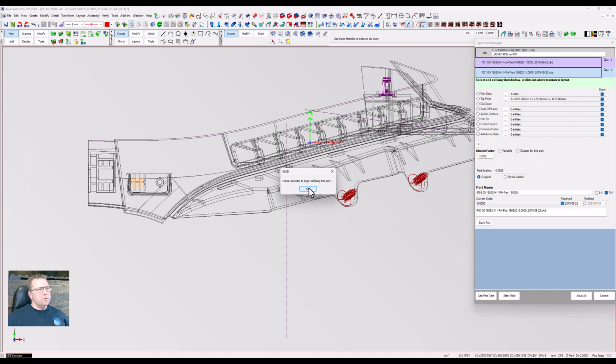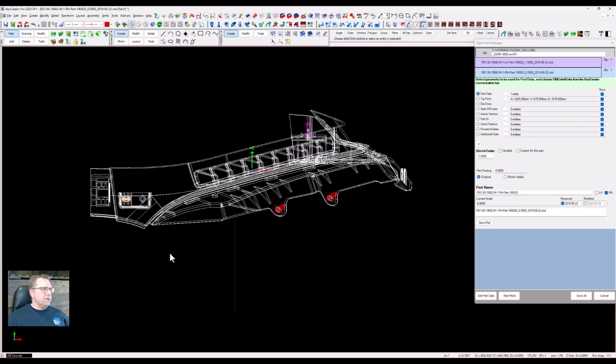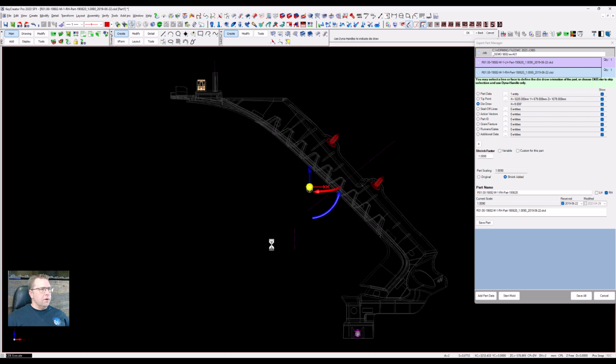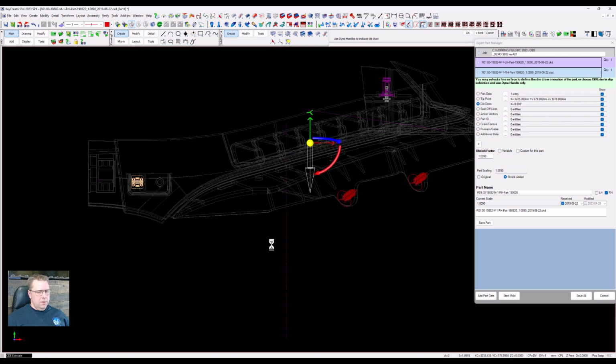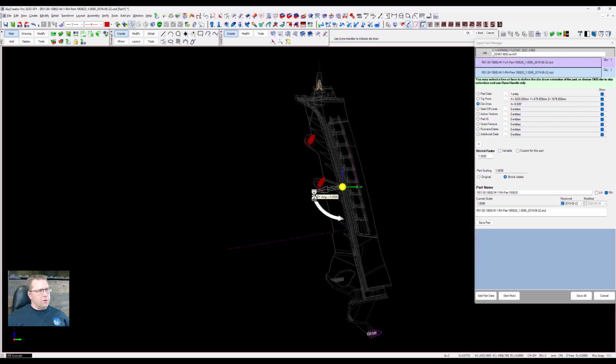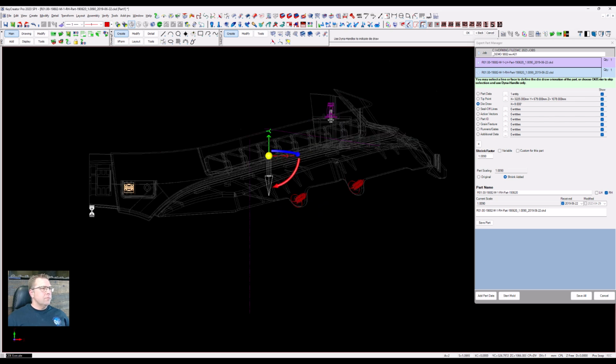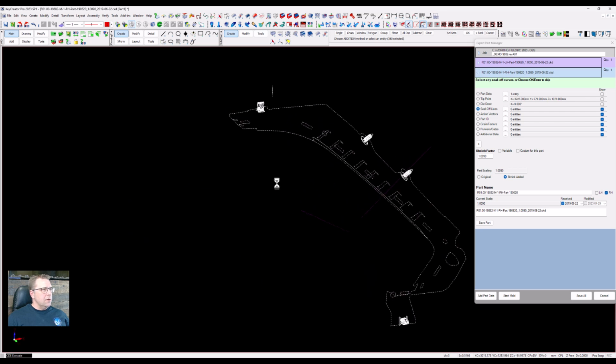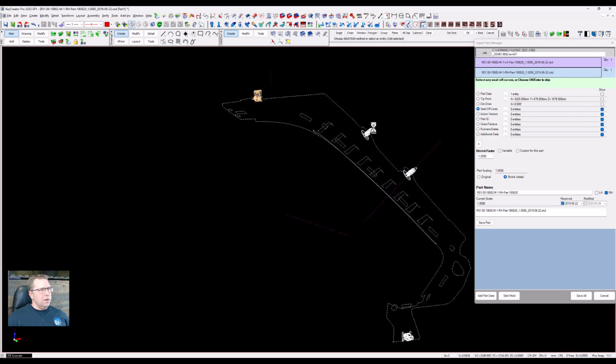All right, second part. Again, I'll change it to black. Already selected the part data. Already has the tip point established, and already has the die draw established equal to the first part, so we don't have to repeat ourselves. XMD is just doing a little bit of processing on that, and if I roll around, go to view 5, you can see the die draw actually matches the die draw line. We'll accept through that. We're going to pick the seal off lines, deselect the action vectors and the solids.